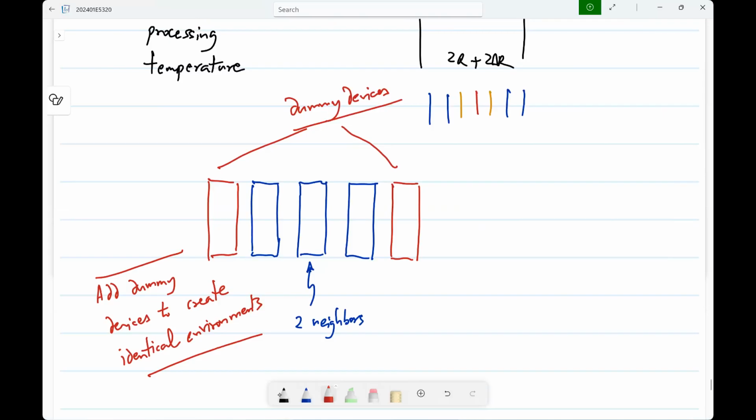systematic mismatch. Systematic mismatch basically comes from things that are known but are usually difficult to calculate and predict. It could be, let's say, a fringing field of a capacitor, which is proportional to the perimeter, whereas the parallel plate capacitance that you calculate is proportional to the area. So if you have capacitors of different shapes, in principle, if you have twice the width, they should have twice the capacitance. But very clearly, the perimeter of this is not 2 times that one, right?